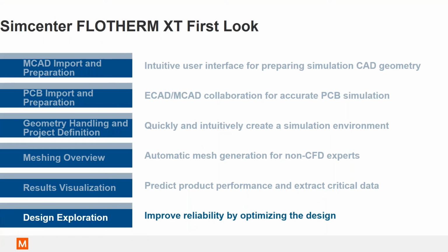To summarize, the benefit of performing a design exploration study is that we define the variant input and let the software find the best available configuration or combination. We have the response surface plot for visualizing, as you saw, the input sensitivities. We clearly saw that the fan position was a lot more sensitive than the vent hole numbers. So the business benefit is that if we can optimize our product, then we are going to improve the reliability of our design, and then reduce the number of respins that we are going to do by redesigning the product.